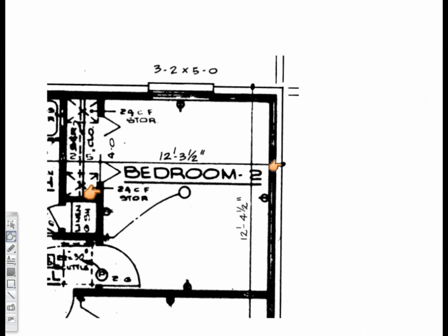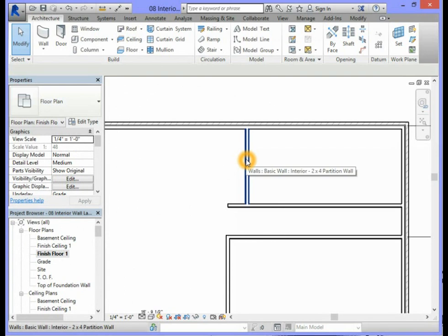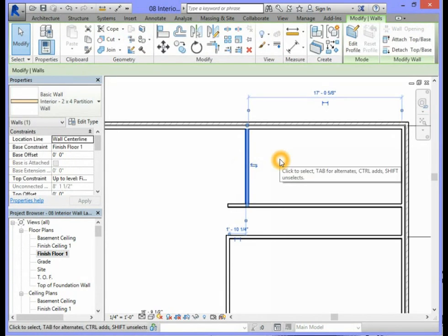To place the vertical interior wall, we will need to use a temporary dimension that goes from the exterior brick material of the vertical wall to the right of the building. That temporary dimension will reference the middle of the vertical wall just created. So to bring up the temporary dimension, we will select the vertical wall.